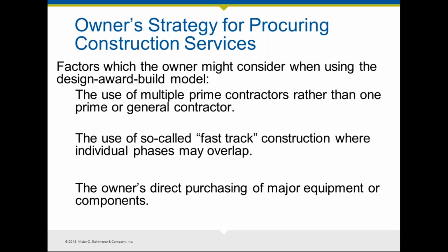So if, for example, they know that they can get started on excavation and putting in the foundation fairly quickly, and you know that you can get the permit for that quickly, you may well decide to go ahead and submit that package for permitting and get started on that piece while the design for the superstructure is continuing on.